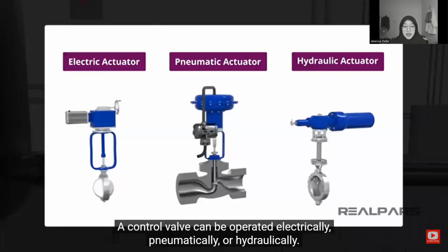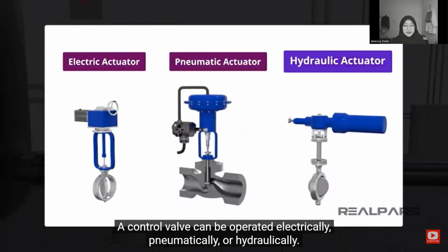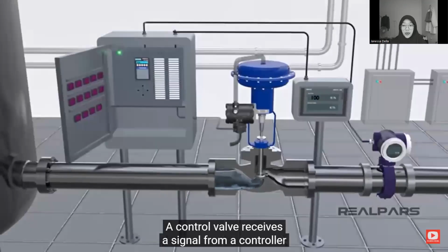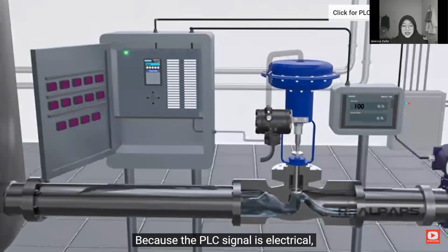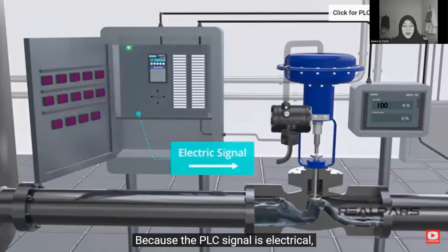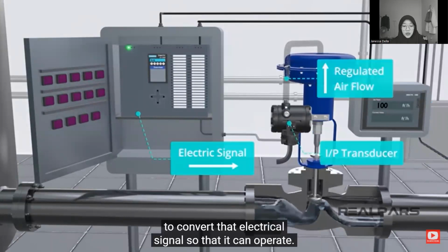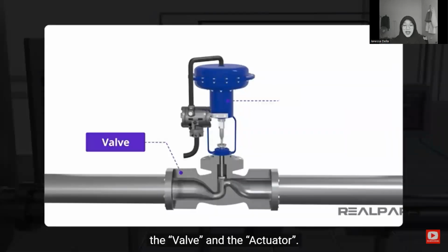Control valves can be operated electrically, pneumatically, and hydraulically. A control valve receives a signal from a controller, such as a PLC, in order for it to move, resulting in a change in the flow. Because the PLC signal is electrical, the control valve may require a device to convert the electrical signal so that it can operate. The control valve has two separate components, the valve and the actuator.